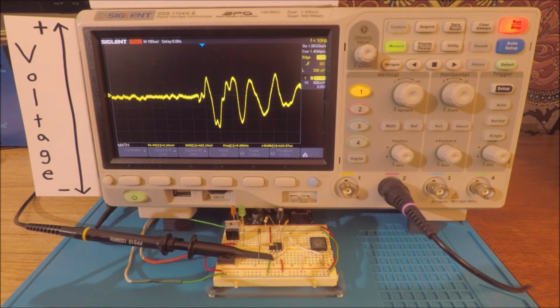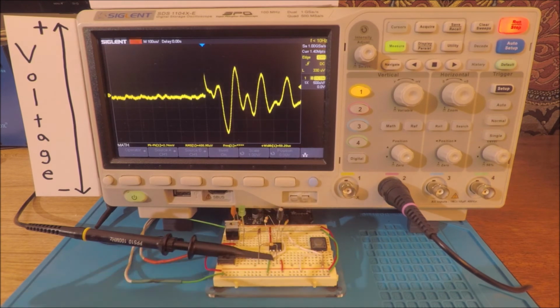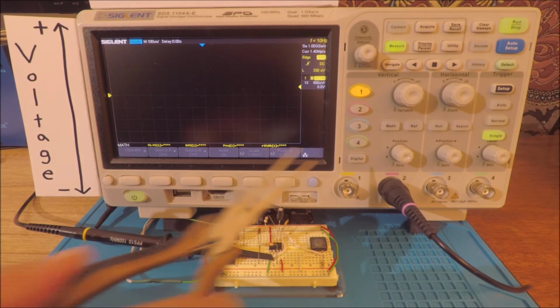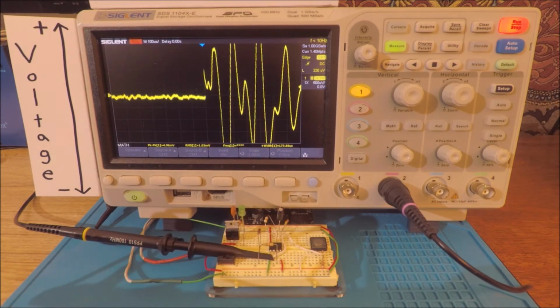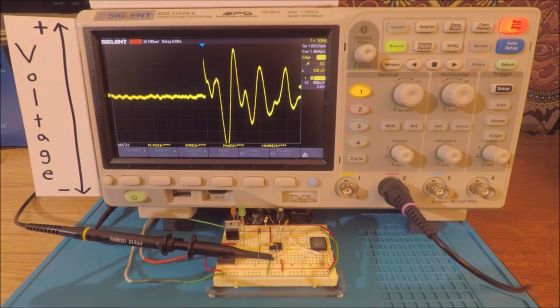Do it very lightly, so we just have less voltage. We can reset the trigger again, do it a little harder. So in this way, you can capture transients by setting the threshold appropriately and placing it in one-shot trigger mode or single trigger mode as opposed to free running. In this case, we're measuring the piezoelectric effect. And of course, this is only good for one shot. So every time you record the measurement, we have to go back and reset the trigger for the next measurement.